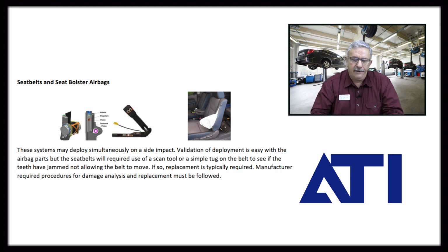One thing I do want to cover that I don't think is covered enough when folks do estimator, repair planner training is, what happens if the car goes underwater? So what are some of the things that you might want to look for? Especially remember that this part for these seatbelt retractors is going to be at the lowest part. That D-ring mounting area is at the lowest part of the vehicle. So it's going to be right in the B-pillar rocker area.